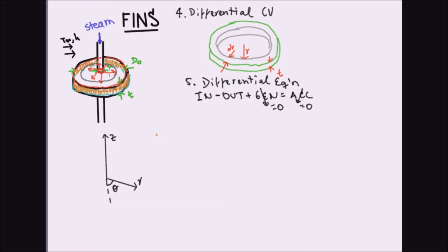These are the ones that we just drew here that flow radially outwards. But notice that there is also another type of heat loss, the convection heat loss, that occurs between the fin and the surrounding air. But let's first start with the conduction one, which is the one perpendicular to the isotherm. So we can draw it here as going from the center into the wall. This is Q evaluated at r, and then we also have heat coming out evaluated at r plus the infinitesimal increase dr. So these are the two conduction heat rates of our differential control volume.